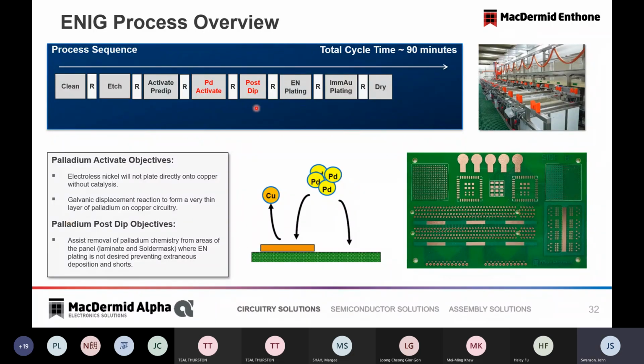If we think about the process, it's a longer process. It is more complex. Here's a photograph of an ENEPIG line. ENIG and ENEPIG would look similar. These are vertical rack plating operations. I'm showing various tanks, and a rack would transport circuit boards through these various tanks in the operation. We go through a clean, etch and activation similar to the other processes.